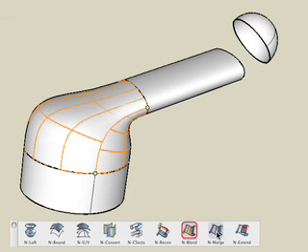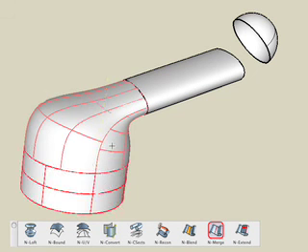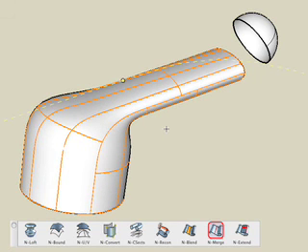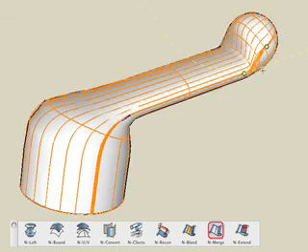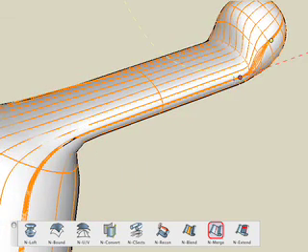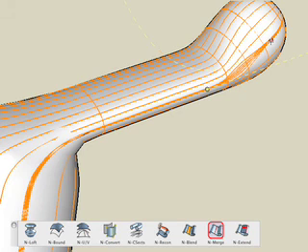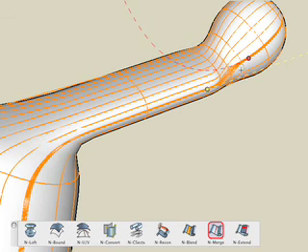Now select the Nurbs Merge tool and click on the base and the blended surface to merge them into one surface. Then click on the handle surface and then on the blended surface to merge those 2 surfaces. For the transition from the handle to the ball, we'll try it directly just using the Merge tool without any blended surface. Click on the 2 objects and adjust the merge position to the desired shape.